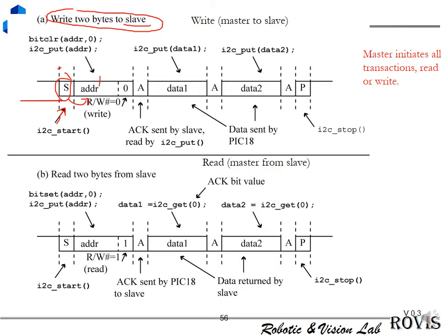The address here is very special, it just has 7 bits. The last bit is very important, because it decides whether we want to write or to read. Here, because we want to write, this bit must be 0. After this step we receive something called the acknowledgement from the slave.